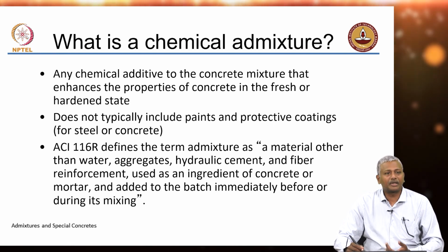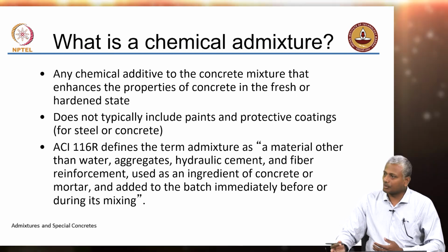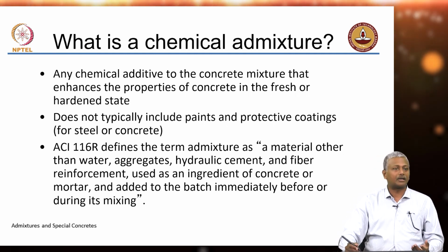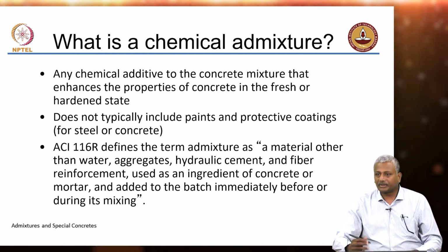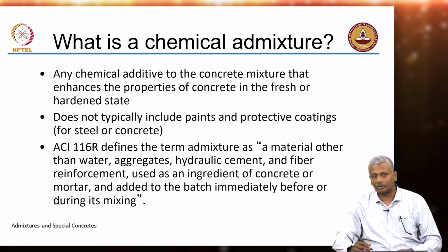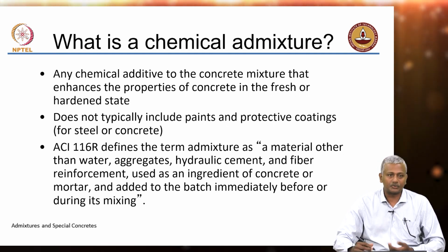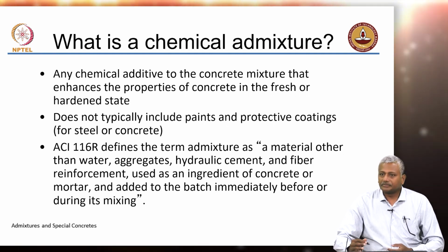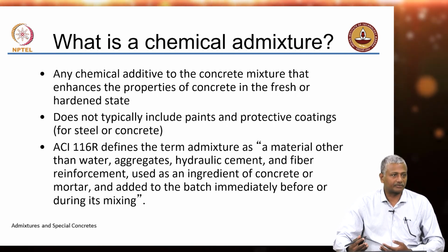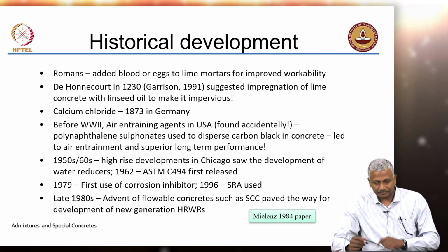Now, if you look at the class of chemicals which are waterproofing agents, there are different types of waterproofing agents. There are some chemical admixtures that you add along with the concrete itself. On the other hand, there are also other waterproofing agents that are actually used as coatings on the concrete surface. You are probably aware of some of these which are used in typical households and so on. But it becomes an admixture only when it is put into the concrete mix, okay, either during the mixing or just before the mixing of the concrete.